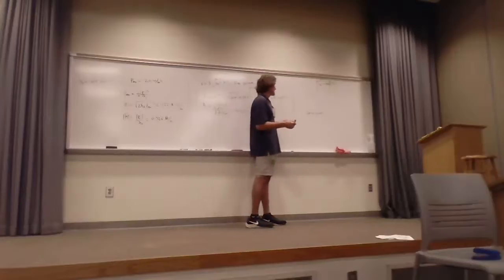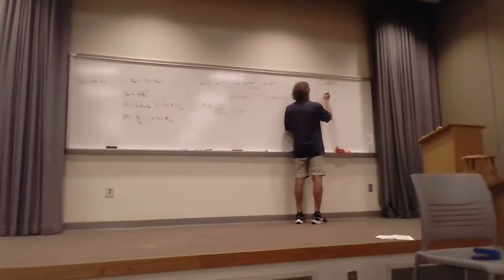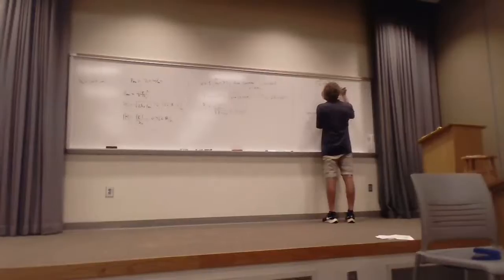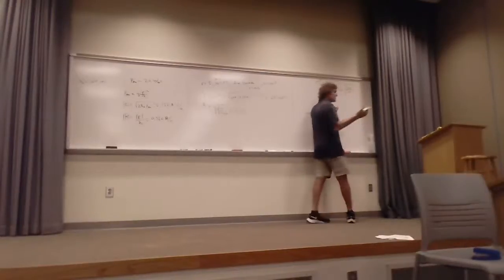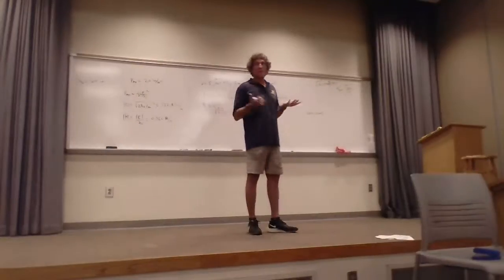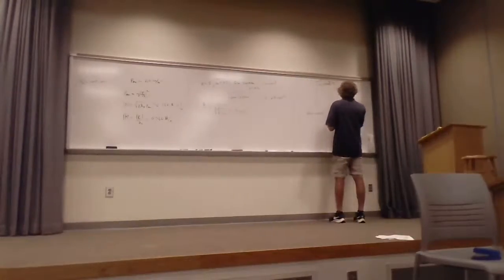There's a couple of things we need to get the shielding effectiveness. First, we have to calculate the impedance of the shield, or the impedance of the copper, which is the square root of J omega mu over sigma. You can just put in sigma, because sigma is so high that omega epsilon is effectively nothing. You can put it in, but you get the same value.